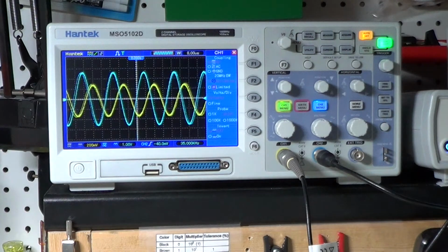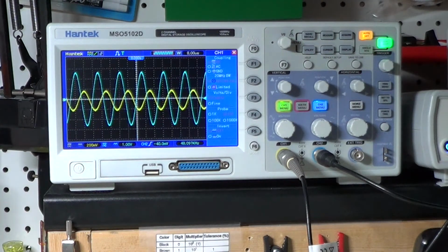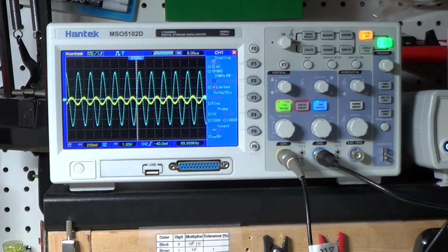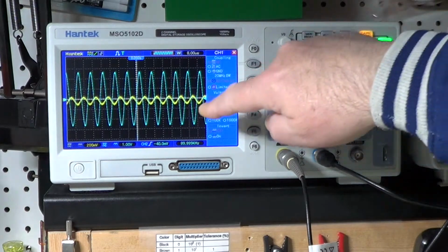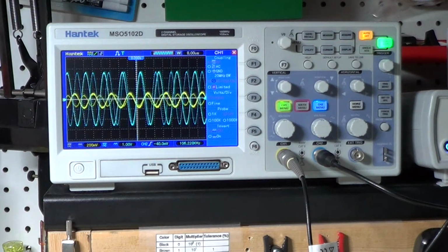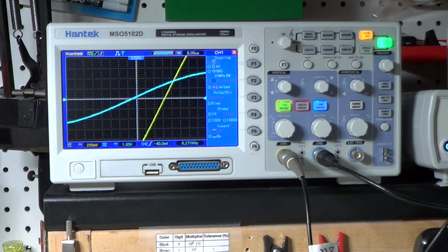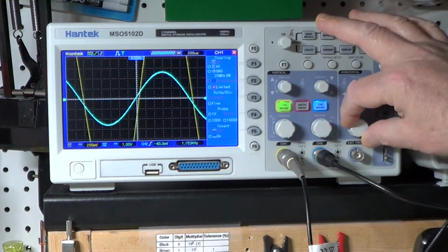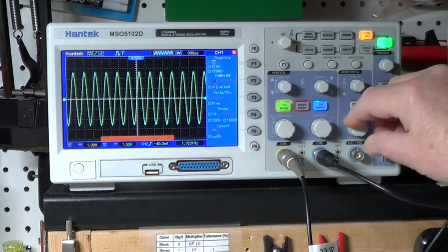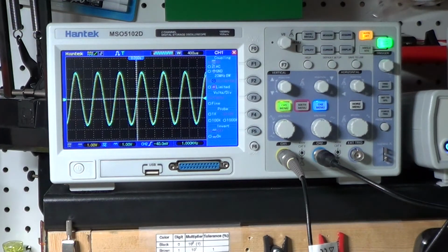So now if we increase even further, so this is 50 kHz, 60, 70, 80, 90. See, the phase shift does not change anymore at this point. It's basically constant at 180 degrees, but the amplitude keeps changing steadily. Now let's go back with the frequency. Let's go back down to about 1000 Hz. And let's put this back to its original value, so we are back at the beginning, like we saw before. So this is for how the voltage, amplitude and phase changes from the input to the output.